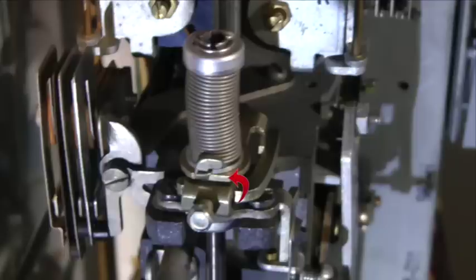This bracket moves up and down with the vertical motion of the shaft, but it does not rotate with the shaft. The bottom of the spring is firmly attached to this bracket. The normal pin is fixed to the shaft, and so it moves up and down with the shaft and rotates with the shaft. It stops the anti-clockwise rotation of the shaft upon disconnection of the call, when it strikes the shaft spring bracket. It also rests on top of the off-normal finger when the shaft is in its normal position. This keeps the off-normal finger released until the shaft moves vertically off-normal. The normal pin clamp anchors the normal pin to the shaft.